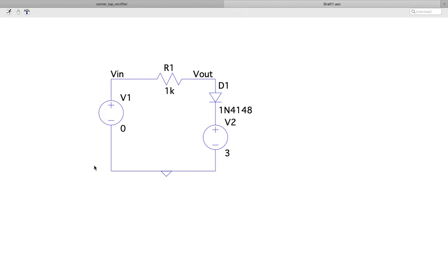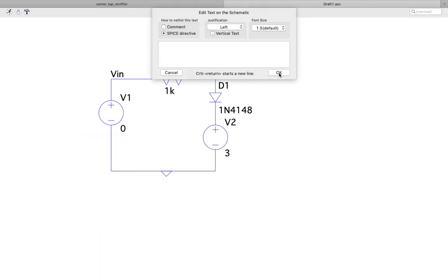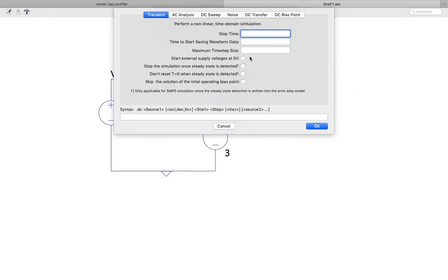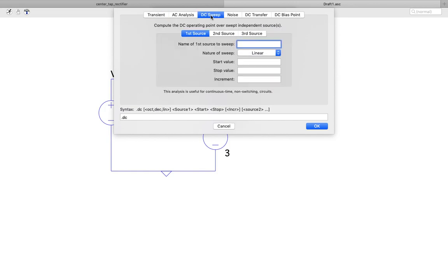For DC sweep analysis, you can just again go to graph spice directive. Because I'm using a Mac version, I have to always right click, and I don't have a shortcut available here, but in the Windows version there are shortcuts available at the top, so you can use that also. So again, operating point analysis. Here you need to go for the DC sweep. Again, I'm recording this demo, so you can go back anytime. I'll be uploading it after the class, so you can always see.